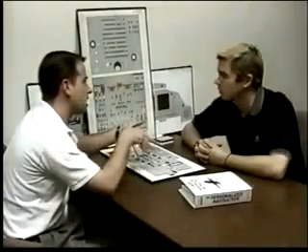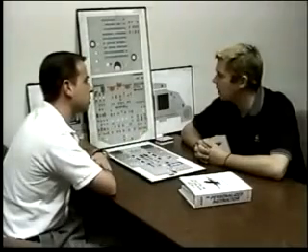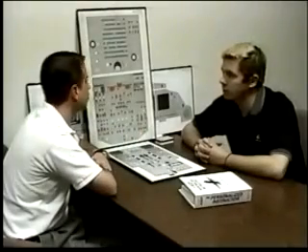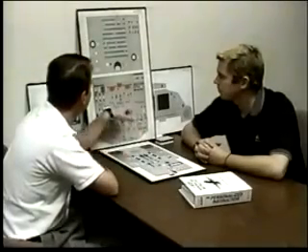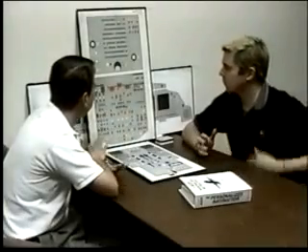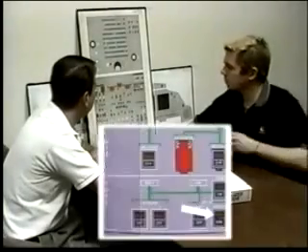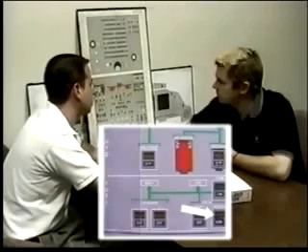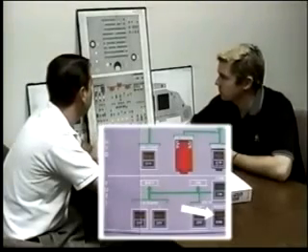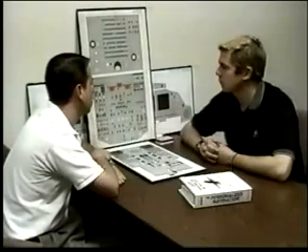Will they close after that happens? Or the inner tanks. No, they won't close until you refuel the aircraft. Going back, you're in flight, you have fuel in all the tanks, and you get a fault light in the mode select switch. Walk me through how you could possibly get into this scenario.